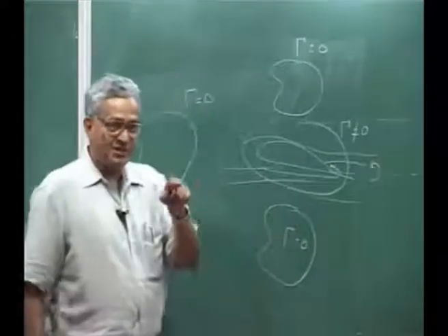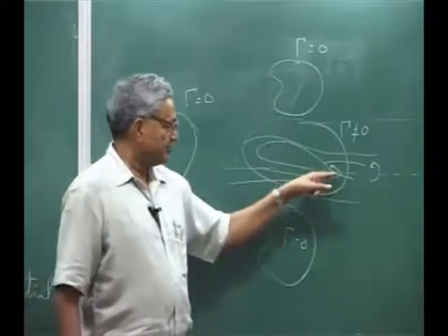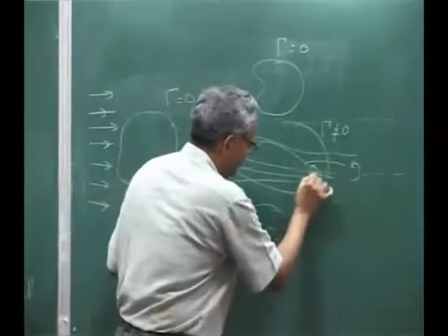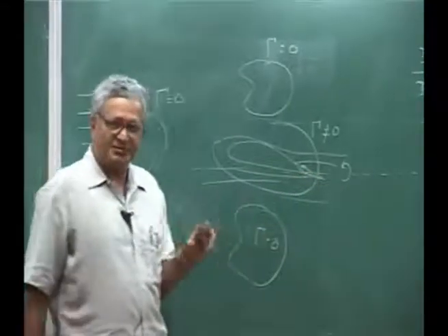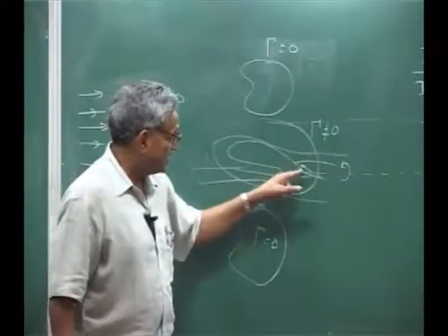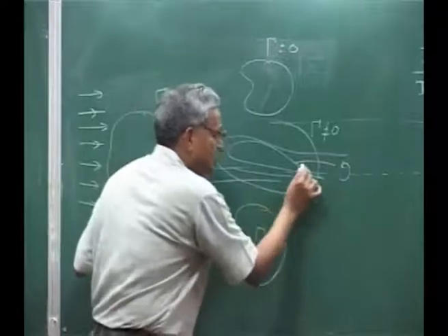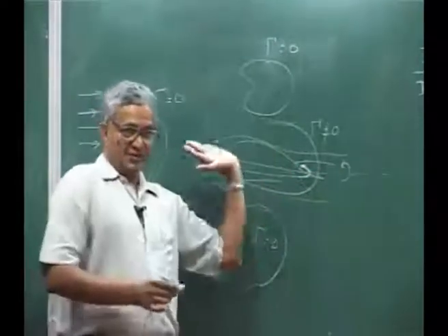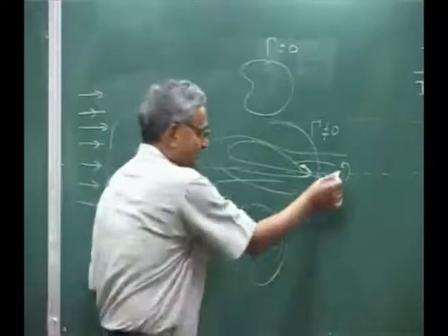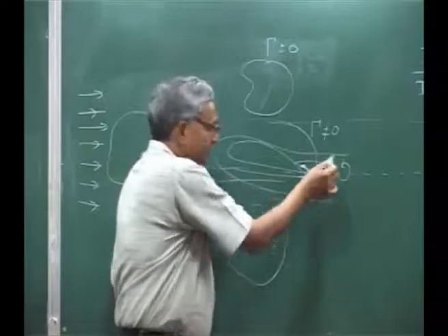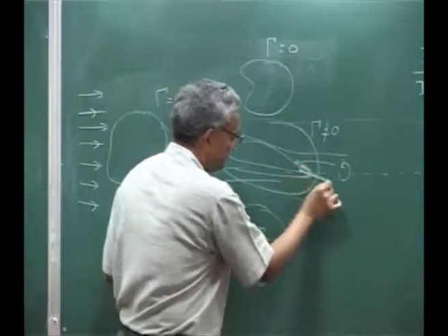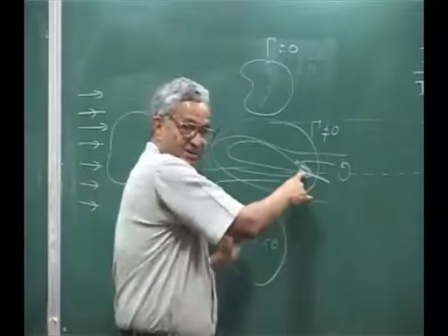That is why for the stagnation point, you make it the trailing edge. But in real flow, it will be something like this. It will go like this. It may extend beyond that. That is because of viscosity and other effects. But here we are neglecting viscosity. When this comes, the flow is going back. When this comes here, that means this vortex will shed. And then this becomes a stagnation point.